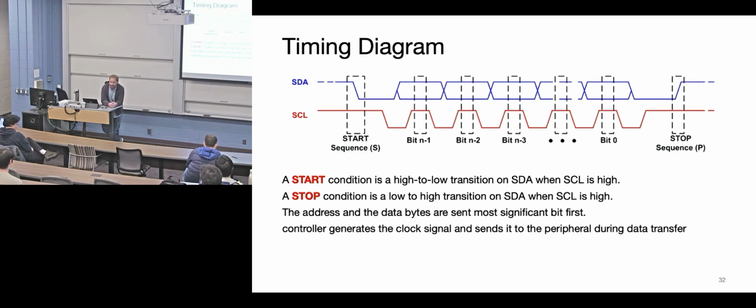How do they check? Yeah, they send it high. They're looking to see if it's high. They try to pull it down, and they hold it down for a little while to take control of it. But basically, there's some negotiation with that start bit to make sure that they can actually use the bus as intended. And then if somebody else is using the bus, the second controller is supposed to back off and just let it occur. You're not supposed to be greedy in this protocol.